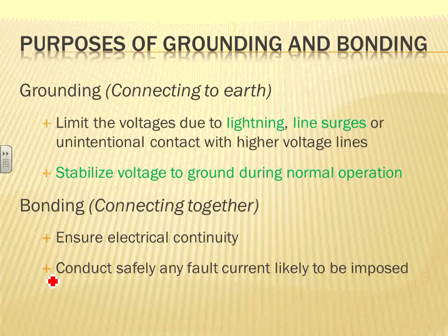Disadvantage, guys, of course, is that especially with VFDs, it burns a lot of VFDs. I heard a lot of people now are going to an impedance grounded system, which is the best of both worlds. Instead of solidly grounded or ungrounded, either on or off, you use an impedance. By having the impedance, you have the advantages of a grounded system, and also you can control the flow of the current in that impedance. Then you have the advantages of the ungrounded system.